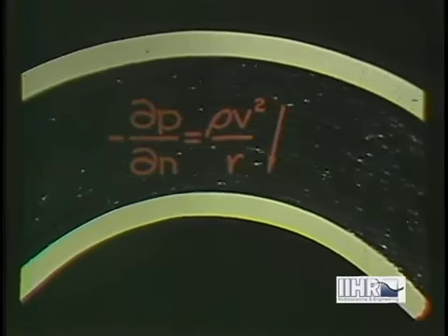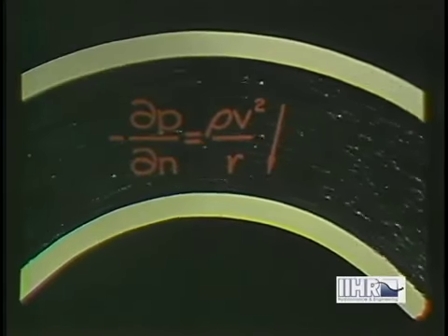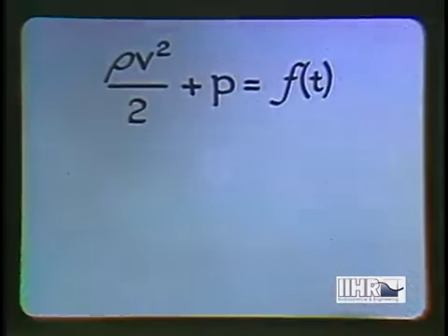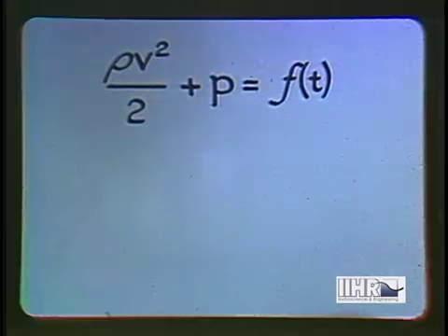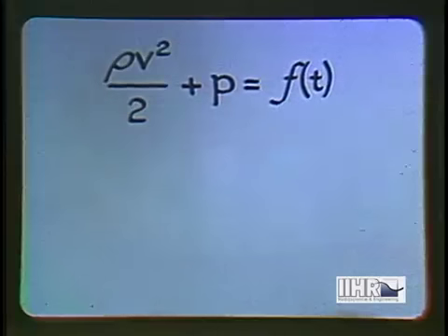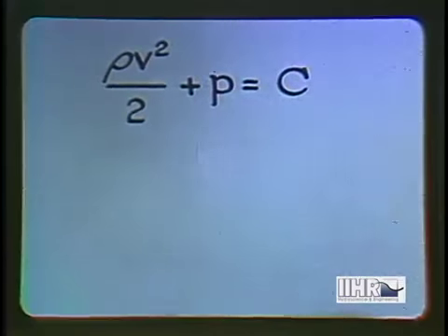We shall discuss a few cases of unsteady motion at a later time. For the present, let us note that for steady, irrotational flow, the equations of acceleration can be integrated to yield a very convenient and significant pressure-velocity relationship. This states that at any instant, the sum of what is sometimes called dynamic pressure and static pressure must be independent of location, but not of time. This sum will be independent of time as well if the overall pressure load does not vary.